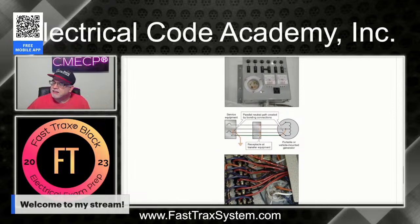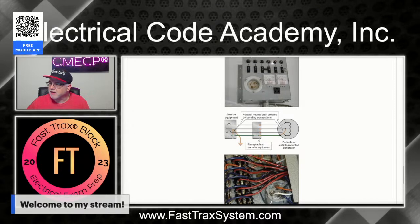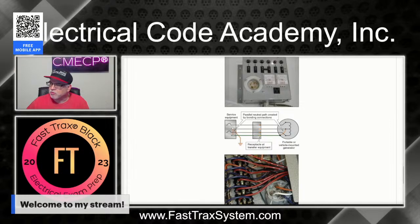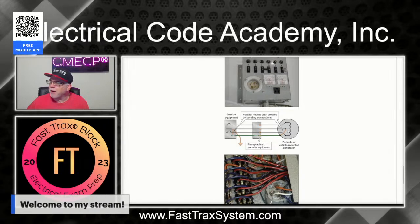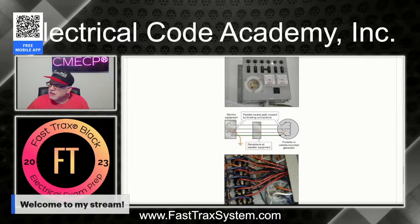All right, so in looking at this transfer switch, you can look in right here, here's your service equipment, okay? And right here, you've got your service equipment, you've got your main bonding jumper, everything's installed, and here's your electrode. So this is your service. And here's the receptacle right here. This piece right here is actually depicting this receptacle, right? So here's what happens. Now, if you go buy a portable generator, and in this case, this is one that is bonded, right? So this is bonded right here.